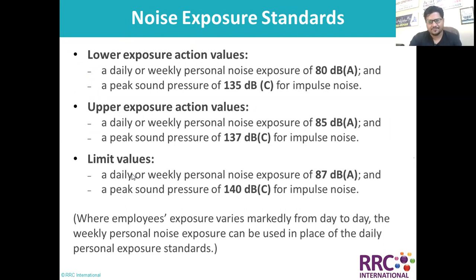In the same way, the noise level. We have to prepare a noise register employee-wise and make sure we are quite familiar with it. Like if I ask about employee number 999, how many hours in 2020 was he exposed to a noise level above 85 decibel, or 86 to 90 decibel, or 90 to 100 decibel? This record gives us a cumulative figure for each employee, and we can also evaluate how that person could be affected. So we can rotate, if we really want to give care to our employees. Otherwise, there are definitely more chances of deafness or some hearing damage.